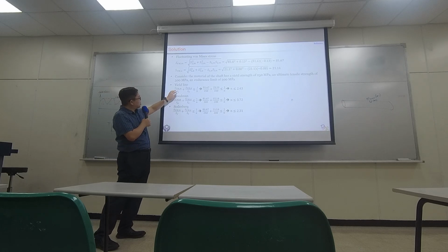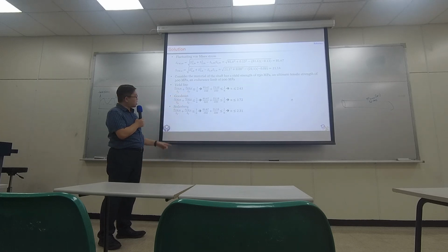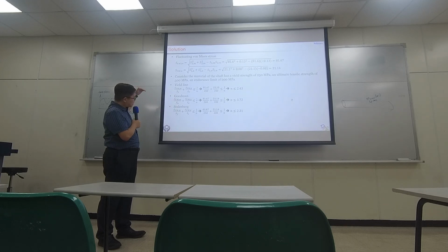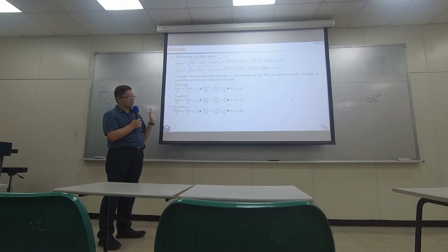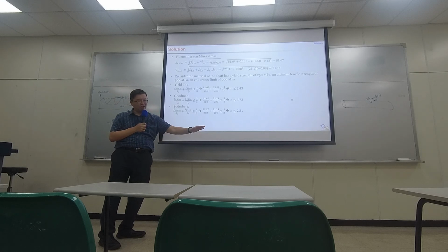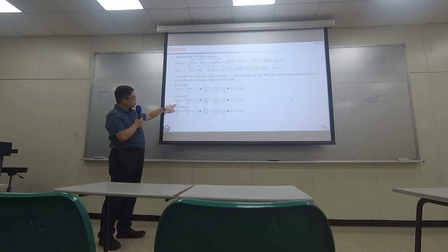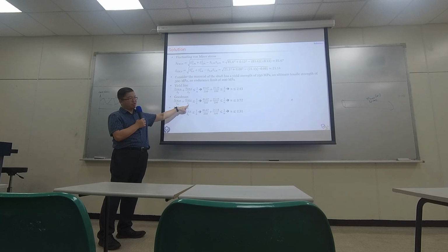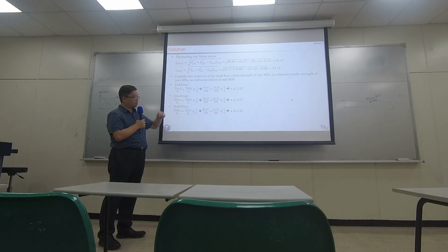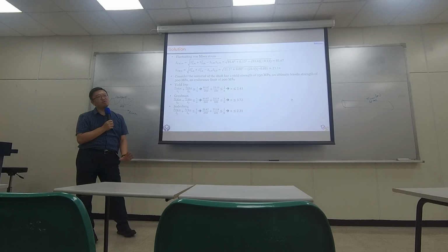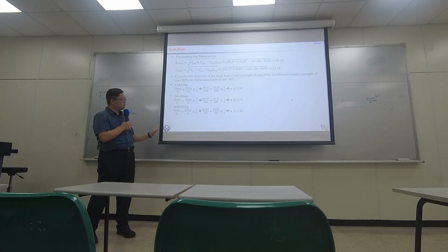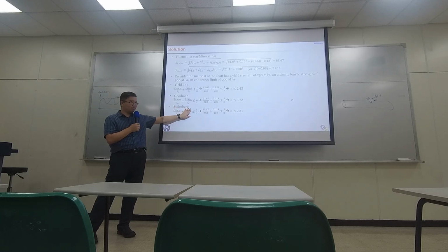The only differences are at the bottom. For the yield line at the bottom, they are both yielding strength. For Goodman, I didn't use the modified one, I used the original one. So the original one is a second line that is more conservative on the amplitude, but more aggressive on the mean value. So the extreme of the mean value is ultimate tensile strength. The extreme for amplitude is endurance limit, a lower value. Soderberg is the most conservative model, conservative both on the mean value part and the amplitude part.